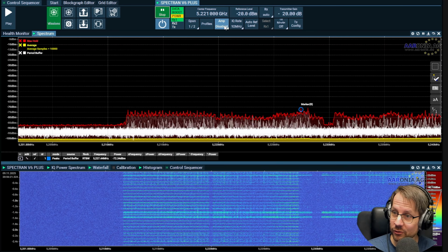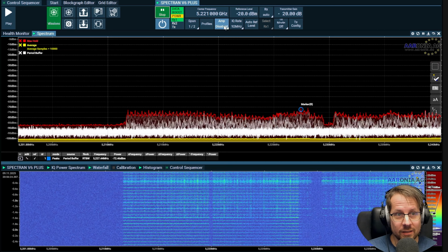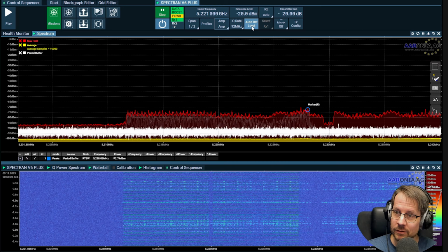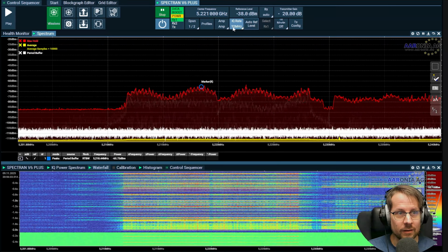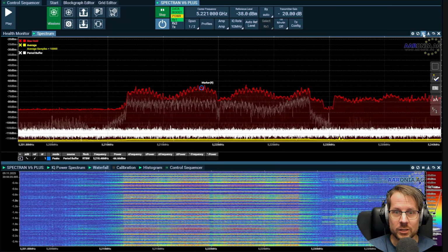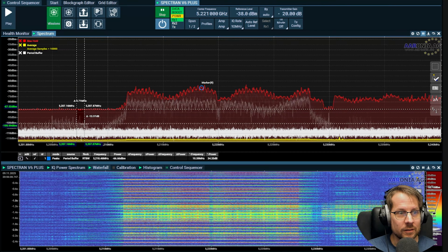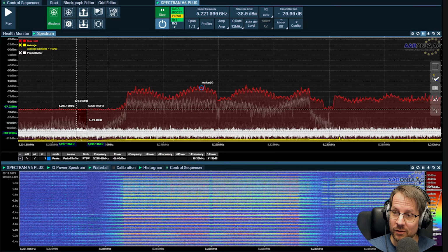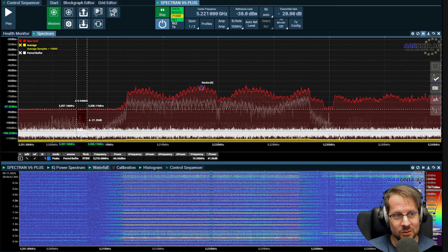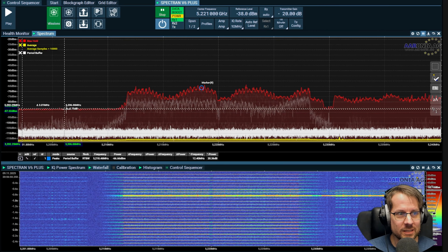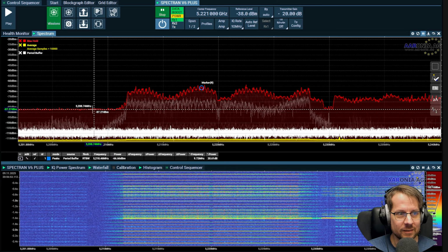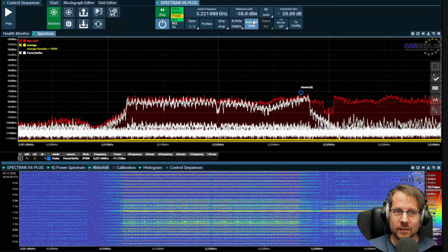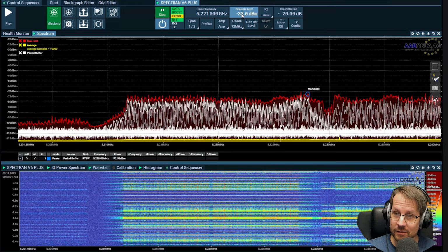So let's first show you what this 20 dB of gain does if I add the amp. And I set the auto reference level. Right? So if you pause this picture now, what happened is that I got around 20 dB better receive sensitivity, right? The LNA gives a perfectly flat 20 dB of gain, right? Really flat, like perfect, right?